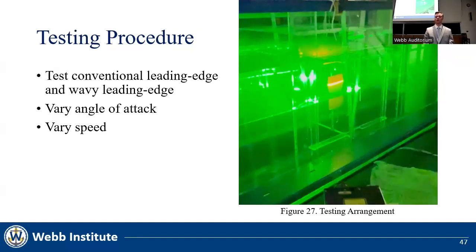It must be adjusted based on the velocities being observed. The particles need to travel far enough for the program to determine the distance and direction without traveling so far that they are impossible to track. The figure shows the laser being fired while recording one of the sets of images. Each set of images was processed in both 2D and 3D because the 2D view from one of the cameras proved to be the most effective for comparing the two rudders.